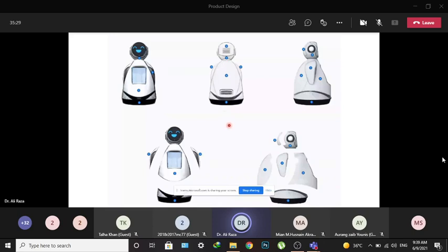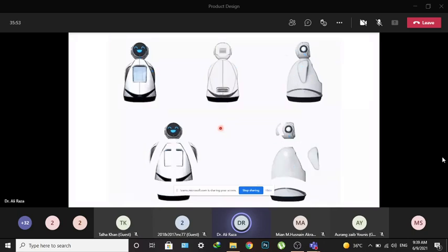And on the basis of that, different proposals were presented that this is how we're going to have different panels made, and then we're going to assemble them together. So assembly lines were identified, the joining lines were identified, the fastening methods were identified, and quite a lot of other discussions went into that. So this is one of those sketches where the assembly possibilities were discussed. This is one of the options. The one which has a lesser number of components is over here. So every aspect was discussed in quite a lot of detail to see what the DFA or DFM aspect of the design is going to be.